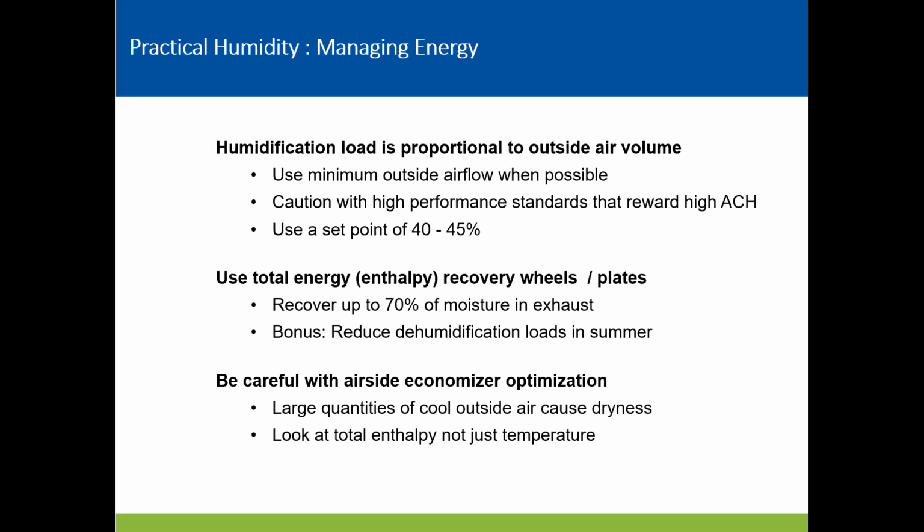One thing to be careful with, some of the LEED standards and some of the high performance building standards will reward very high air changes per hour. And a lot of operation strategies might look at using economizer type systems in the spring and fall that can bring in cool outside air and cool the buildings. But what that's going to do is it's going to drive indoor dryness and can require additional energy to bring the moisture level back up.